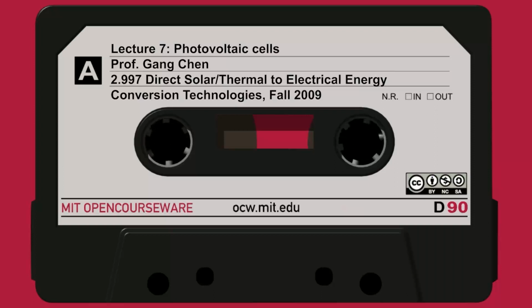And this basically changes the Fermi level. So what we end up with is the Fermi level actually increases, so as you increase the number of electrons, the Fermi level will increase, and when you remove an electron here, you end up with a hole here, so you basically decrease the Fermi level here. So you end up with some kind of region which is basically the open circuit voltage that we see.